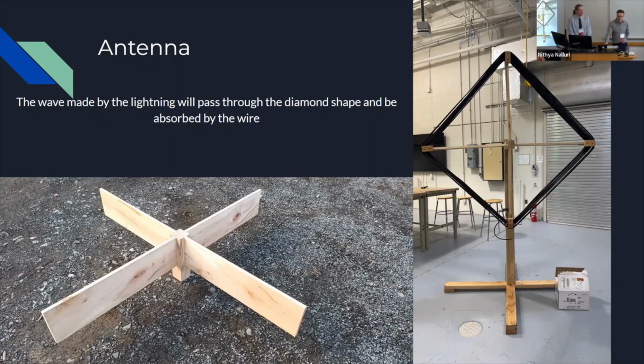We had to use RG6 coaxial cable for this because it's a lot cheaper than 50 ohm coax. So after connecting the coax port to it, we actually got 75 ohm to 50 ohm adapters to screw onto the end, so we get a bit of loss. Actually, you could have just looked it up directly. The SWR wouldn't have been that far off.